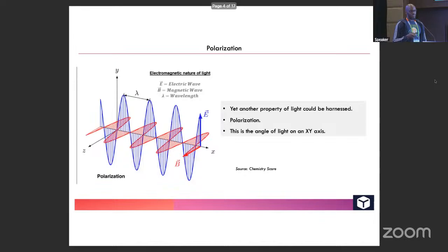And to add on top of that, we also add polarization. So if you have amplitude, you've got phase, and you've got polarization, you now have 3 attributes onto which you can encode data. And all of that is what makes it possible to move from 10 gig, 40 gig, all the way to 100 gig, up to 2.4 terabit, as we are seeing right now.